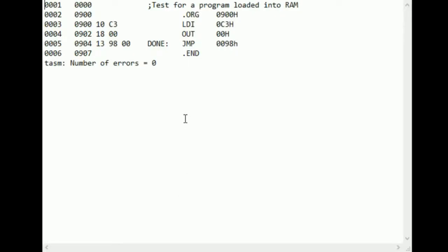I've written a brief program to demonstrate the run routine. This is a listing of the program. The assembly language is over here, and I ran this through the TASM assembler program using an assembler table that's specific for the new processor, and it generates the object code, which is here, machine code, and puts it in a list file that also has the memory locations that I've assembled it to.